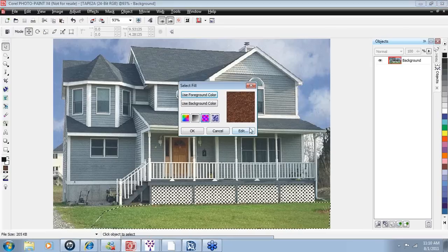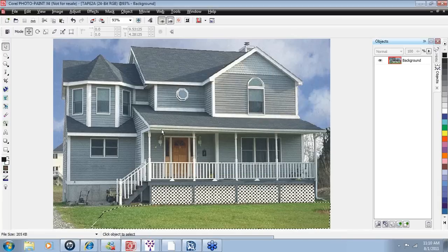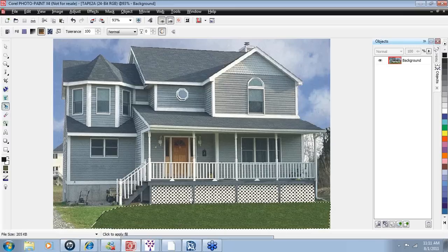Loaded in EARTHSCAPES, ready for you to work with and use, are your different textures. So we do have mulches and grasses, paver materials, leaves for barren trees. You can also add your own textures, and this means different pavers, different crushed stones, different types of mulch. You're limitless in terms of what you can add to this texture palette. Well, we'll go ahead and select the grass texture, and we'll use our fill bucket. You'll notice that my cursor has changed into the bucket icon, and I can simply just left-click inside my mask line, and we have a new lawn that's been established.